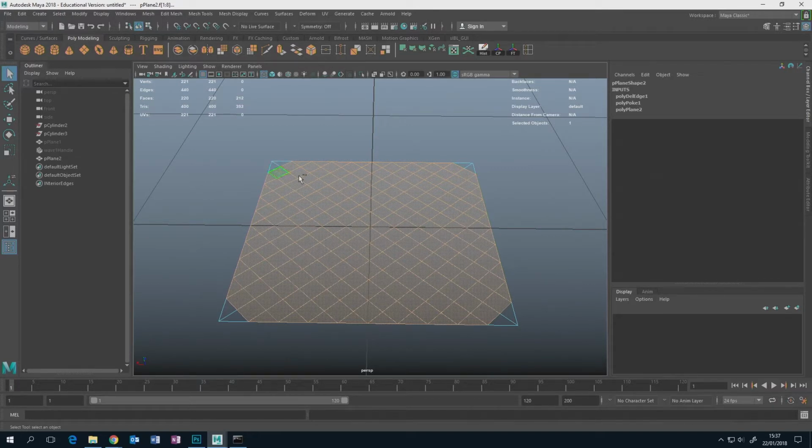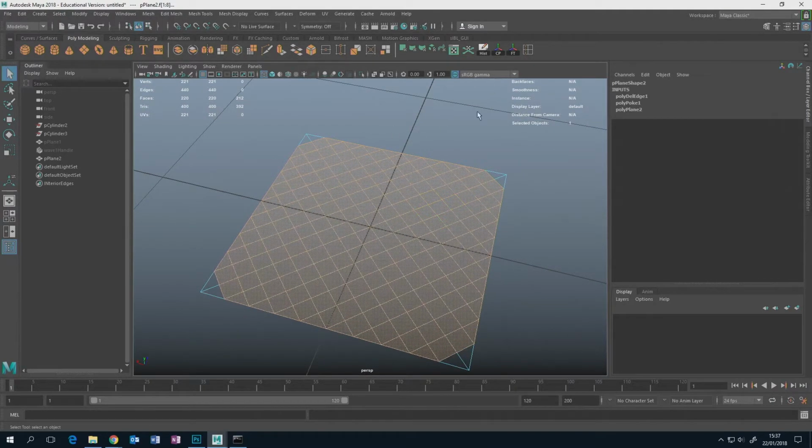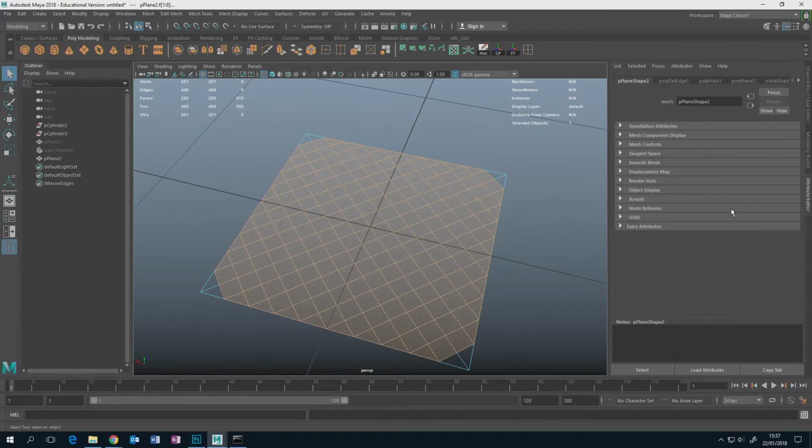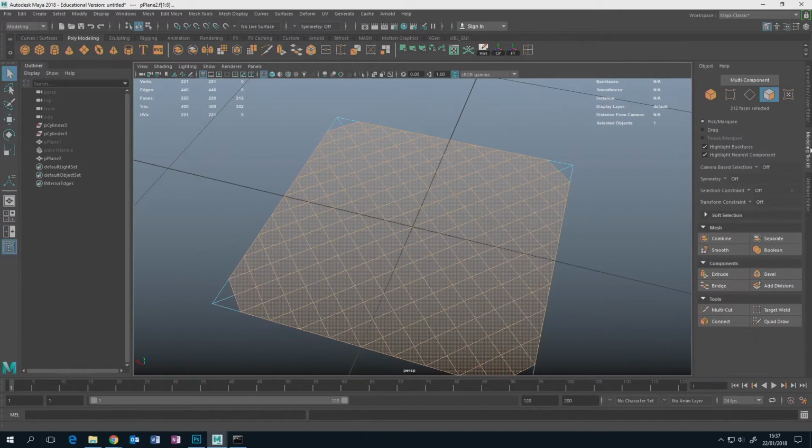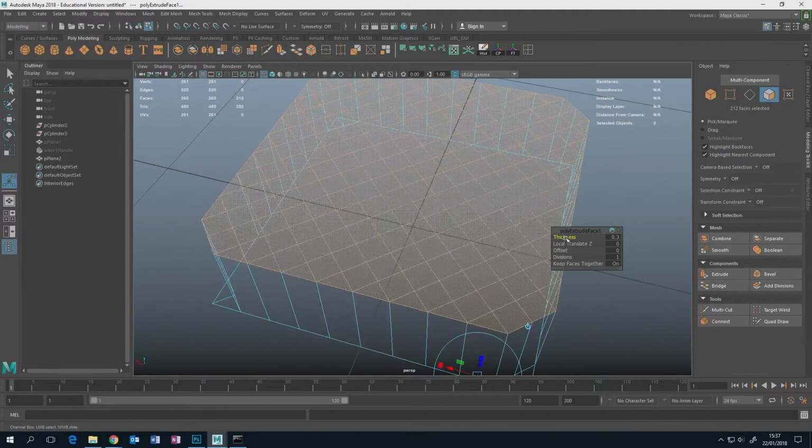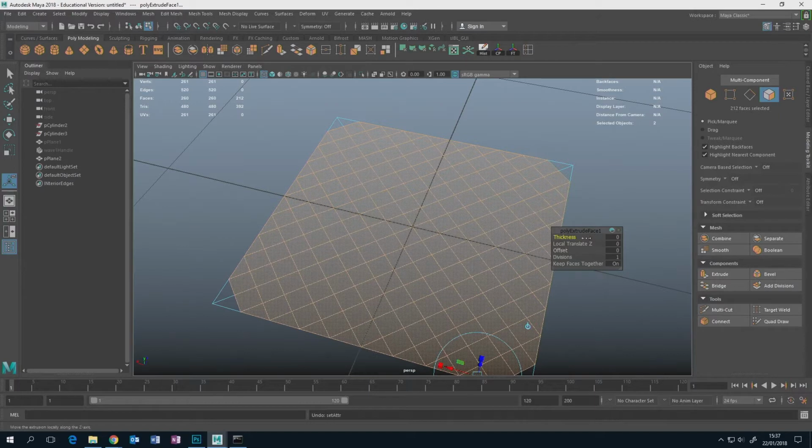But now I want to get rid of all my original horizontal and vertical edges. Well, I created the selection set here, so that's actually quite easy. Just go in here, interior edges, and delete them. And remember, when you want to delete edges or vertices, you want to hold down Control and delete. And now I've got that kind of pattern. But why would you want this kind of pattern? What use does that actually get you? Well, you can do effects like this.